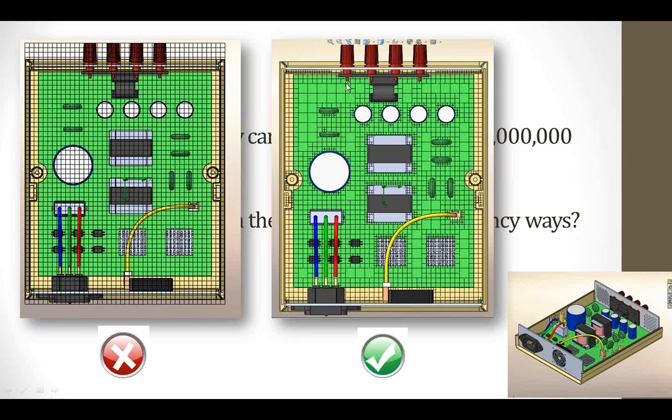There's no point for us to calculate here, so the meshing here is only about 20 cells. However, when the region is near the electronic components, the meshing starts to concentrate. You see here, the meshing is around 1000 to 100, but around here it is around 10 to 20 only. So this is a powerful way of meshing. For this powerful meshing, around here the meshing is nicer and makes our calculation time better.